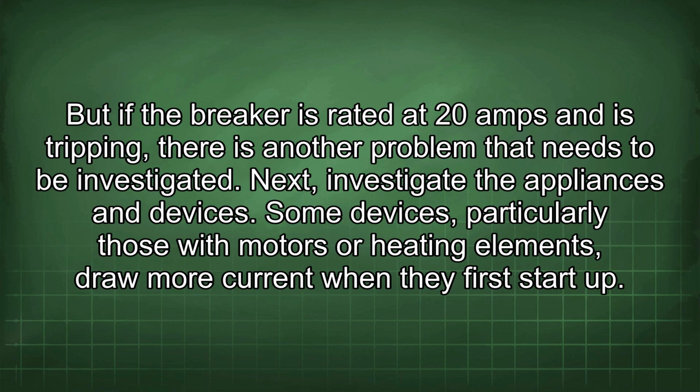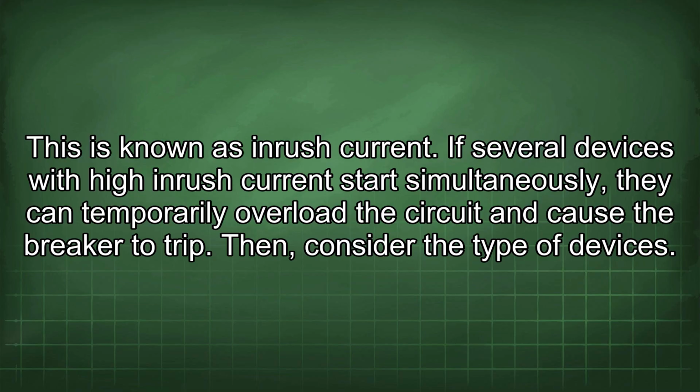Next, investigate the appliances and devices. Some devices, particularly those with motors or heating elements, draw more current when they first start up. This is known as inrush current. If several devices with high inrush current start simultaneously, they can temporarily overload the circuit and cause the breaker to trip.